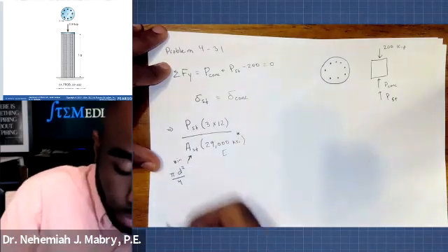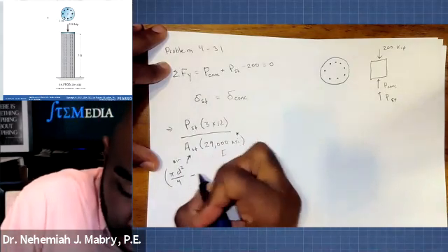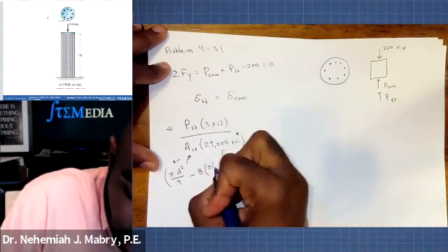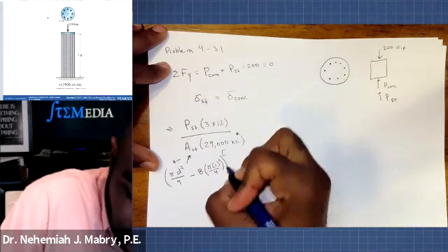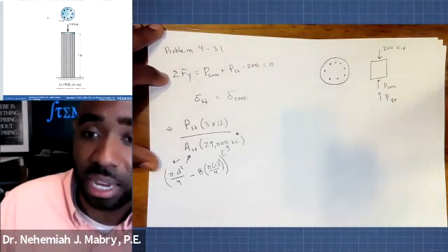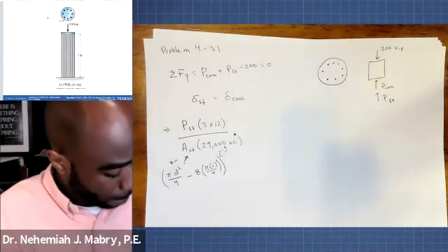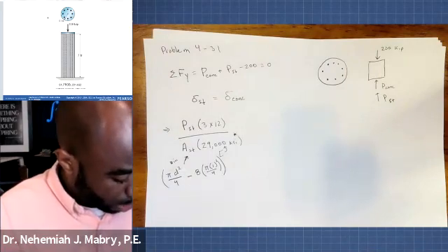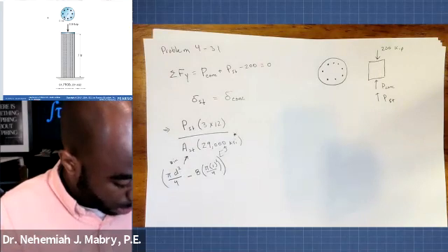So remember that. That is the area of the entire cross section. But from there, we're going to need to subtract 8 times the area of those individual rods. Eight times the individual rods. And so we could actually calculate that right now. Pi times 8 squared divided by 4 minus 8 times pi 1 squared divided by 4.